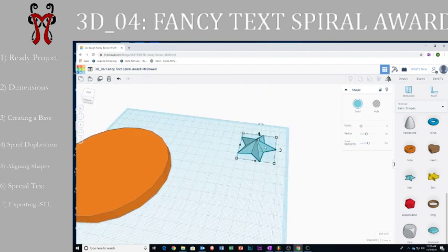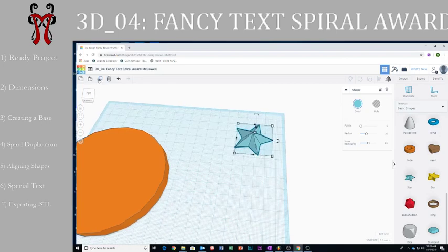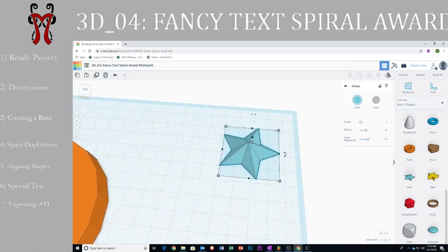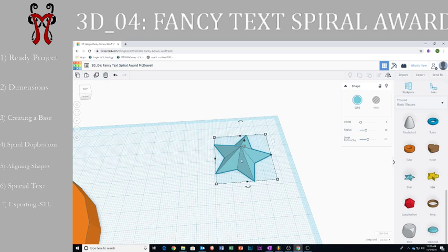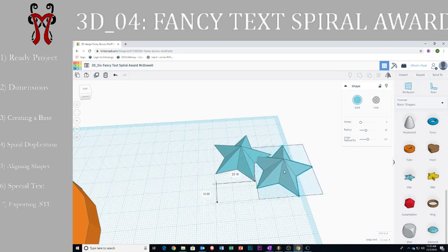First thing I'm going to do is click on the object that I want to duplicate. Then up here on the top left, you're going to see something that says duplicate and repeat. So I'm going to press duplicate once, or you could press Control D, and you'll notice that apparently nothing happened. Actually, something did happen. The object was duplicated. However, the duplicate of it is inside of the object. So I'm going to move that object, and you'll see there's a second one in there. So I'm going to move this a little bit off to the side here.